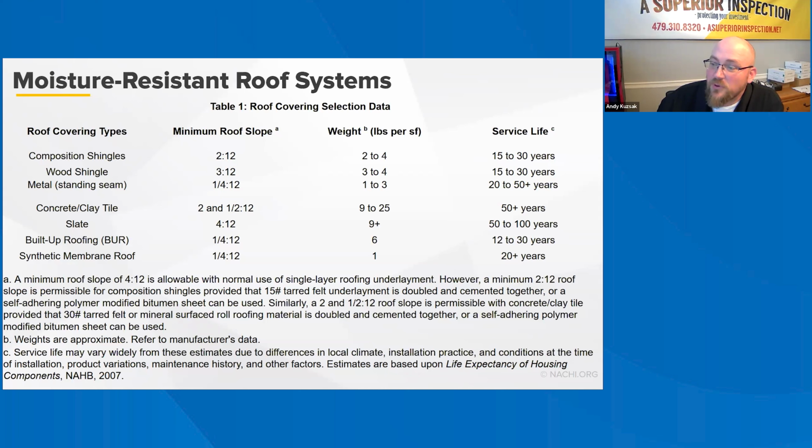So for roof slopes of 4:12 and greater, 1 layer of underlayment should be applied in a shingle-like fashion. It should start at the eaves and run parallel to the eaves. It should overlap 2 inches. It should be fastened sufficiently to hold in place. End laps of the underlayment should be offset by at least 6 feet.